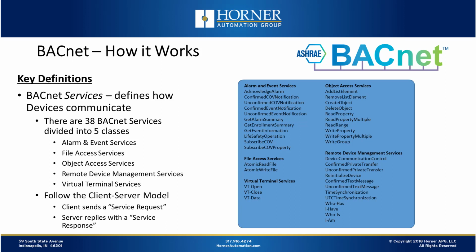Now, in addition to defining objects and then the properties that reside within those objects, BACnet also defines what they call services. And these are services that really define how devices communicate with each other. Just like there's a whole slew of predefined objects with BACnet, there are a whole slew of predefined services as well. And those are organized into 5 different classes that I have listed there.